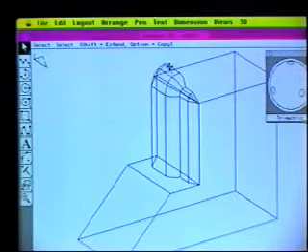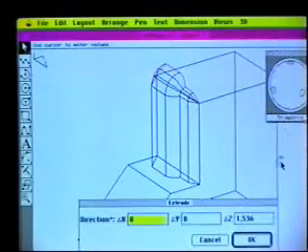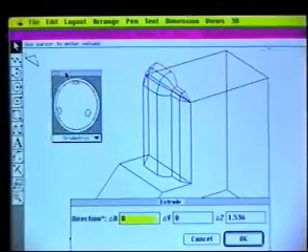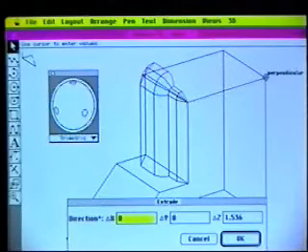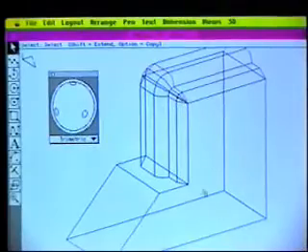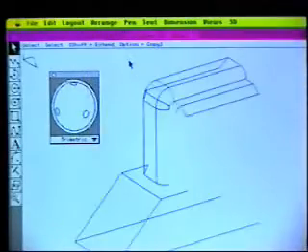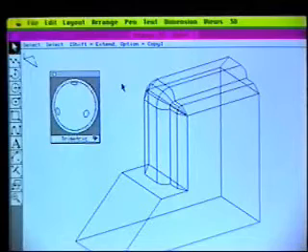Now I'm going to pick the same 5 objects that are on the end of the revolve and do a final extrude, and extrude these across the top. Now I'll move my trackball out over here, and then just go in and define my extrude to be from here to here, and then say OK, and that happens automatically. Now I will do another zoom all so that we can see this. And there's my complex contour that's been taken across my part.